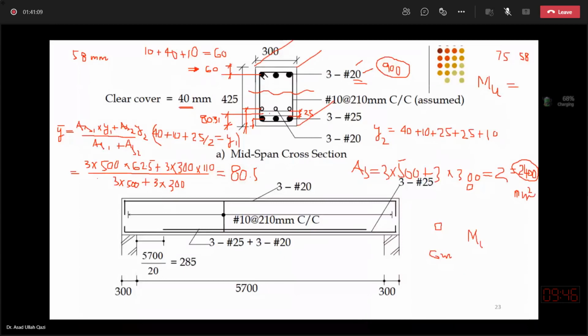If your WU comes out to be greater than or equal to 70 kilonewton per meter, I will be satisfied that my design is okay and I have case 2 doubly beam in which tension steel is still at yield and I have the phi, whether it is in the transition domain or in the tension controlled under reinforced domain. So what phi you will get.